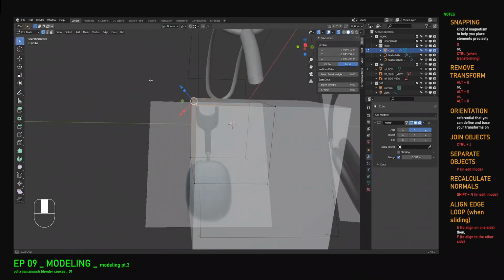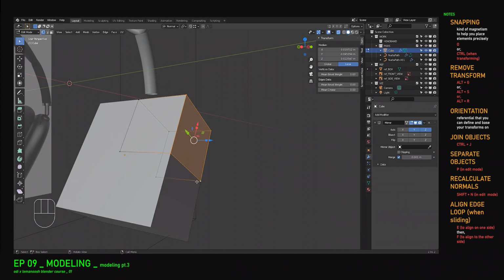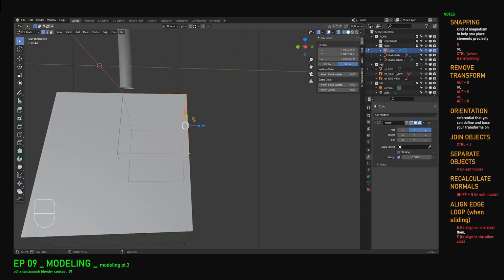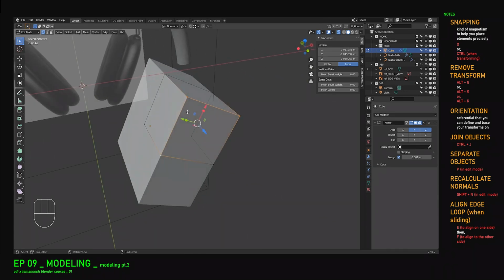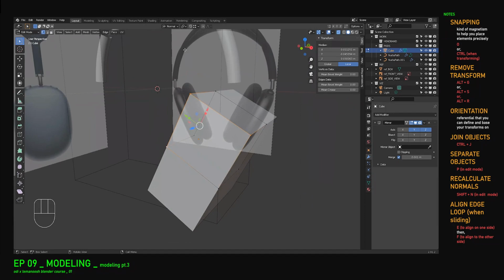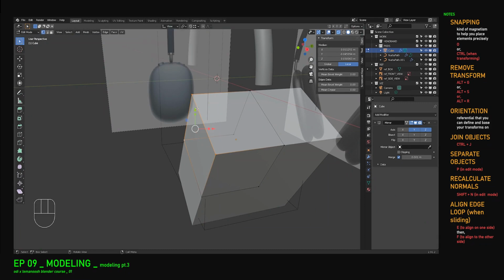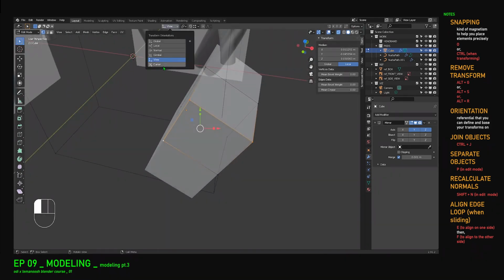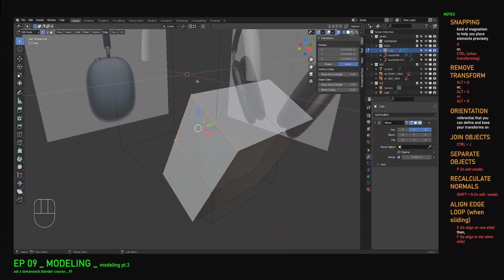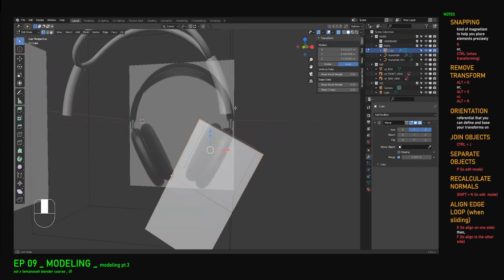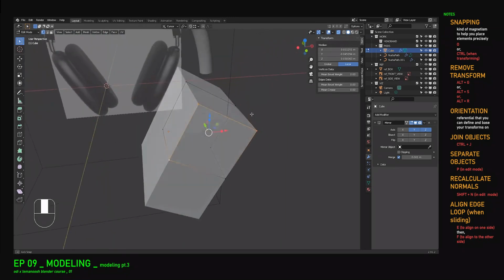Normal is not the same, but it's kind of like if you have a face or just 3 points, it will actually show you the perpendicular to this theoretical plane that is created and 2 other directions. Then you have gimbal, which I couldn't really explain, view, which is quite simple, and cursor, which depends on this little thing that we didn't talk about yet, but it's not as necessary as it used to be, though I use it a lot. I will show you later on why.